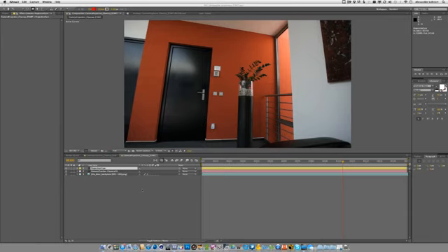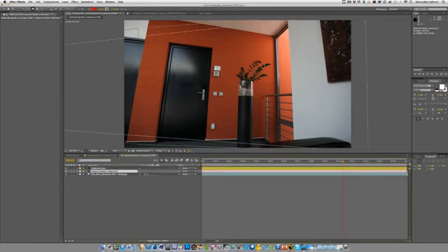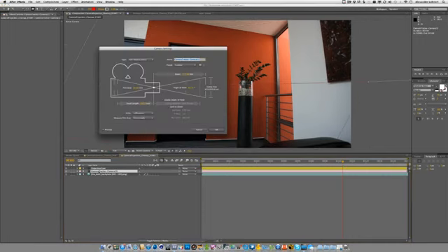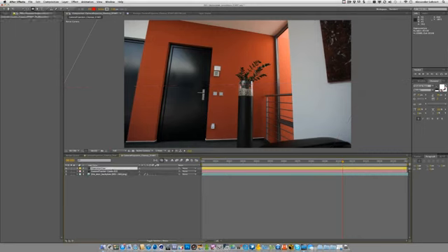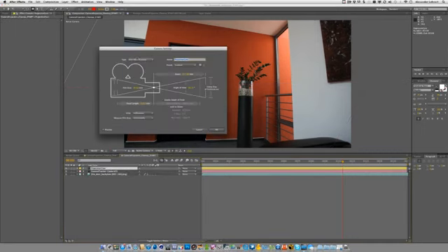Okay, so for your projection camera settings you have to make sure that you don't miss one important fact. Your camera tracker camera is a 2-node camera, so this means that you've got position and an anchor point of your camera. But we don't want that for our projector, so just make sure that we get a projection cam that is a 1-node. You can even just change that in here and it's immediately changed to a 1-node camera, which is only holding the position and the rotation, but not the anchor point.